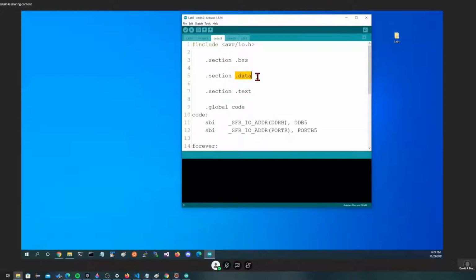Now it's a little tricky. Basically, you're going to declare a byte of data and a label, probably, which is going to be mapped into the SRAM. Because it's initialized, that doesn't mean you can't change it. It just means it's initializable. Then the initialization number, because there's nowhere else to put it on this chip, will be put behind the program in Flash.